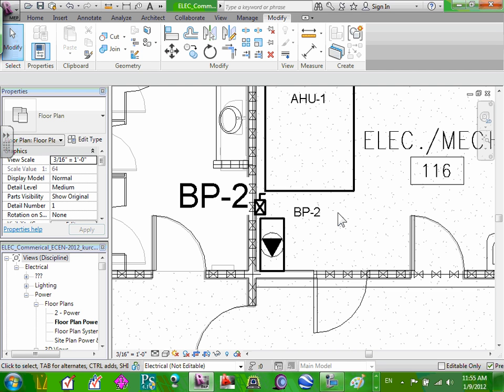Really, for all practical reasons, when you pull, Nick, why did we circuit? You know why we circuited? We circuit because when we pull a panel schedule, I want the panel schedule to show BP-2 next to the circuit. It will show it here. So what would adding a disconnect to it mean? Not a whole lot in terms of inside the panel. Now, if I come to wire right now, there's a BP disconnect and a BP equipment. I'm going to bring my circuit to the disconnect, and from the disconnect, flex it to the equipment. So it doesn't add value to the system.